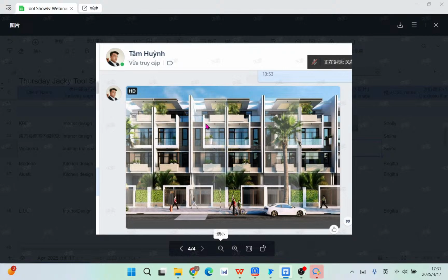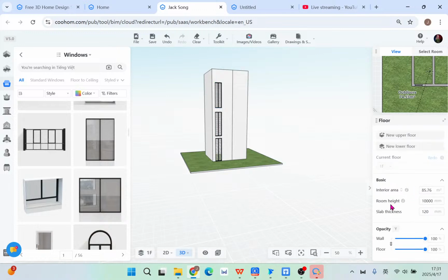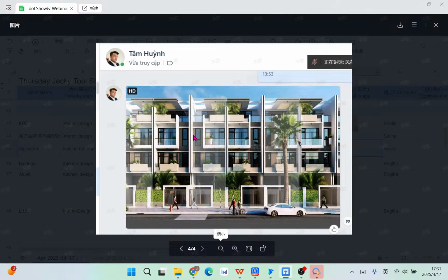But the key thing is that it really requires at least the same level of the surface. And of course, sometimes you feel like, okay, if these two share the same section, the same front surface, it's just different between the balcony because it extends to the outer. Can we just draw these two levels in one floor? Yes, we can do it. You can control the room height in different levels. You can settle level 2, level 3 into the same level.